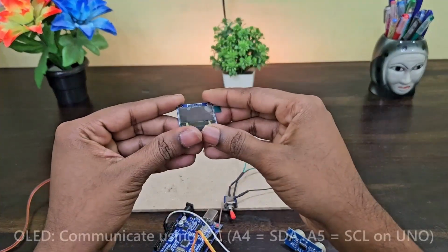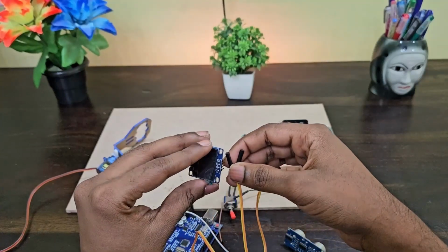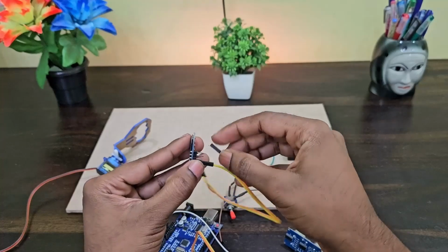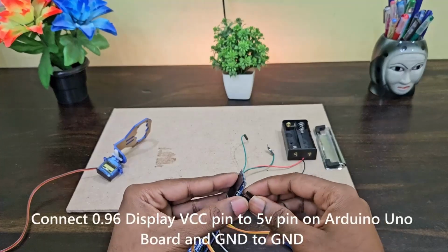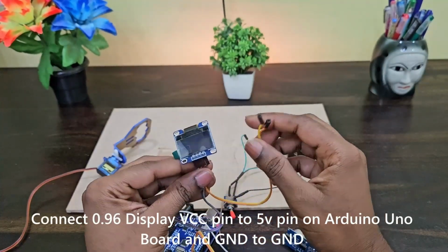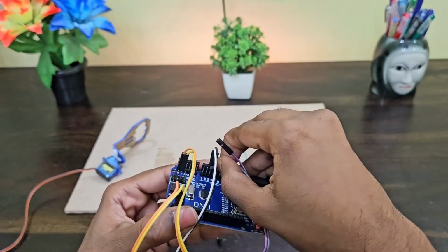For environmental sensing, we are using the BMP180 and OLED display. They communicate with the Arduino via the I2C protocol. A4 is connected to SDA and A5 is connected to SCL on the Arduino UNO. The BMP180 gathers temperature, pressure, and altitude data, while the OLED display brings it all to life with a radar animation. With all these components working together, the system detects obstacles, gathers environmental data, and visualizes it in a radar-style display.